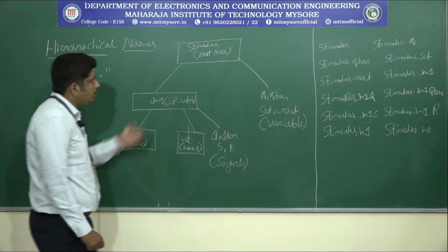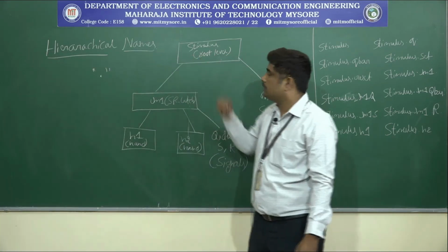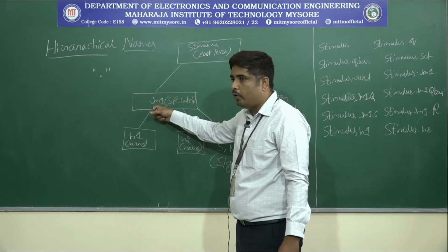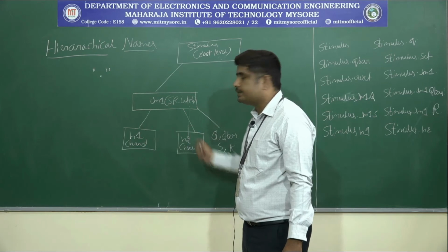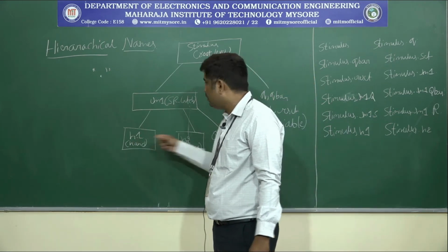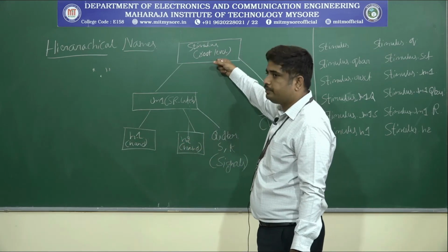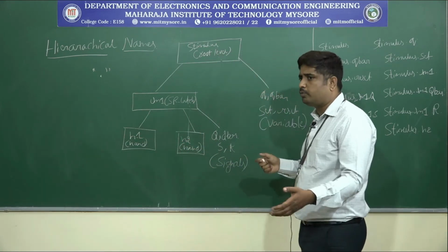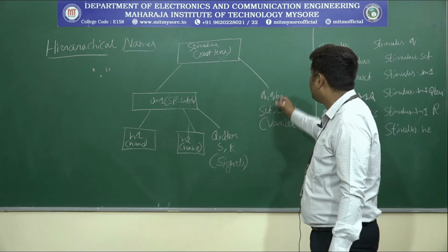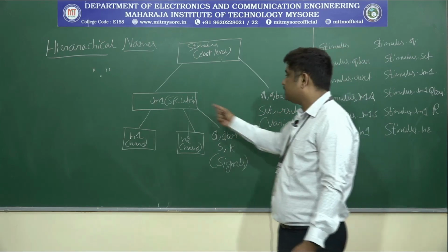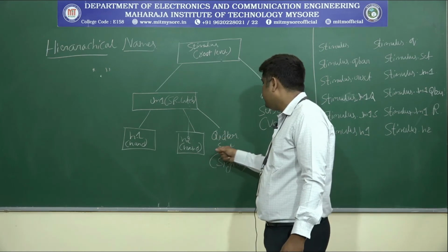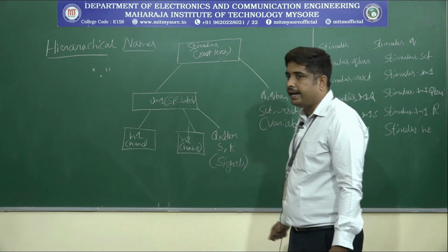Let us assume the stimulus is what we name the root level. After this, the SR latch we name as M1. Then the SR latch requires two NAND gates, NAND gate 1 we name N1, then N2. For the root level we can't assume inputs and outputs, so we represent them in terms of variables. The variables are Q, Q bar, set and reset. For the SR latch we directly mention the inputs and outputs, that is Q, Q bar, then S and R. These we call signals.